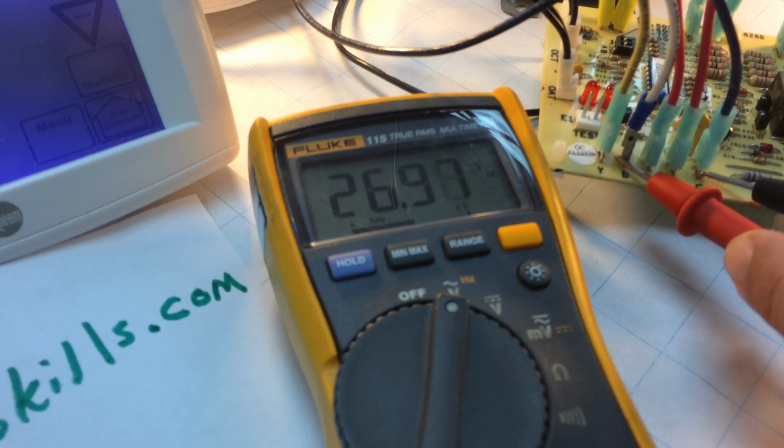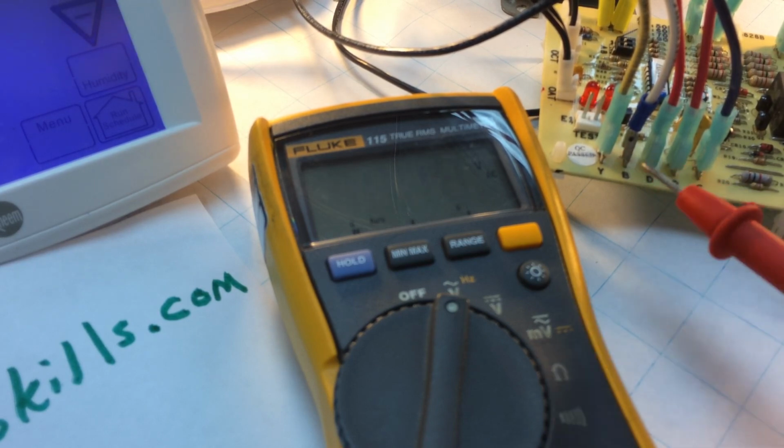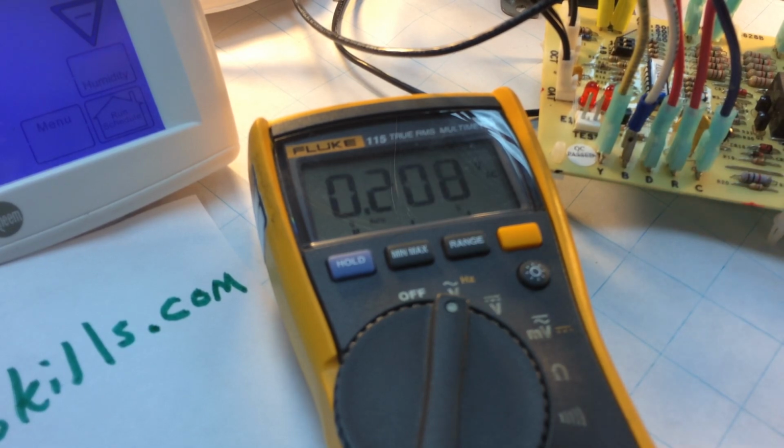So I have 24 volts, or a nominal 24 volts, from common to B. This signal will always be there as long as the thermostat mode selection is in the heat position, just as a system that energizes a reversing valve in the cooling mode is always going to have O as a live output whenever the system is set to cool. It doesn't have to be calling for operation.